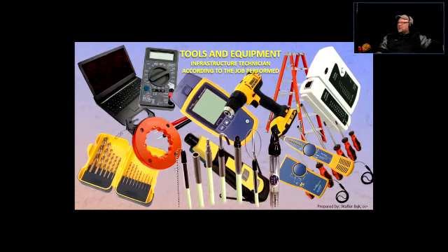Okay, and then this one here, you can see a chain. That's very useful because you can push that thing with a chain into a space in the wall, and where it comes down to the opening, you can push in a telescopic magnet on a stick, and that magnet is going to catch the chain and pull it out. It's all about making the job more efficient.